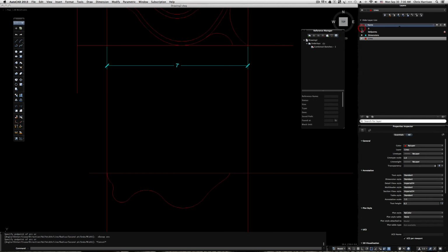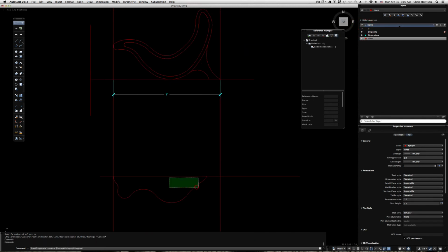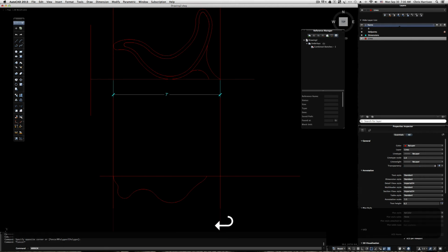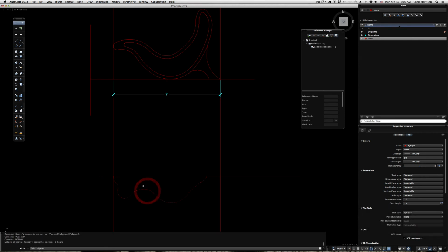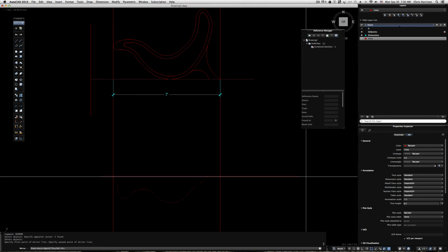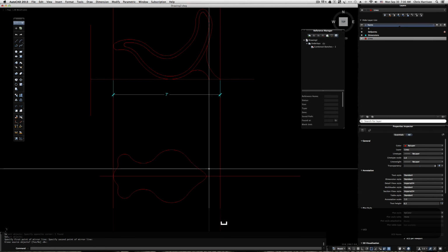Now I'm going to turn off the image again, and you'll see that I'm left with this half of the shape. I'm going to type in mirror, select it, select point to point, the axis that I want to mirror the plane on. It's going to ask me to erase a source object. No is the prompt that's given to you, the default rather. I'm going to hit enter, boom.